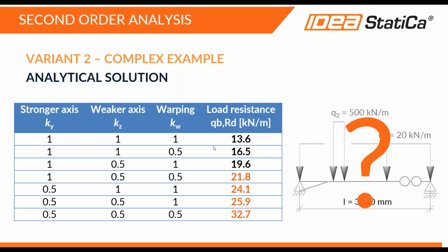And here I did this neglecting the local load and neglecting the openings. I made just a small table where I used all the rows from the table that describes the rigidity of the supports. And I concluded with this. So if I made a big mistake, obviously, if I would consider these supports hinged, I would end up with this value of the resistance.